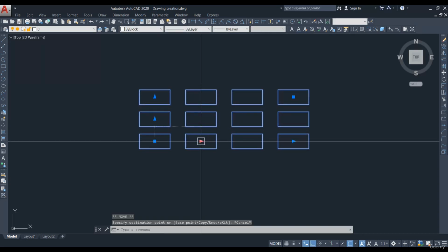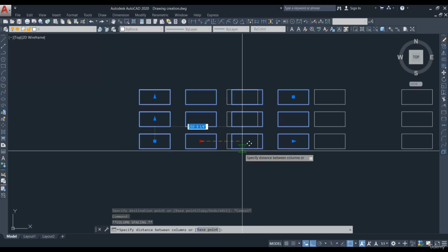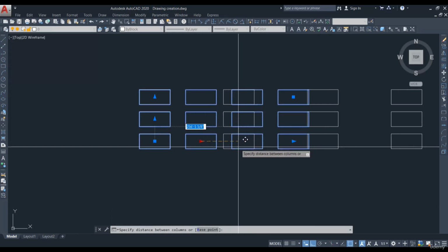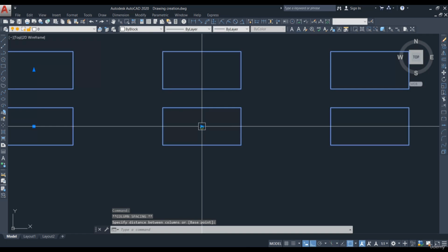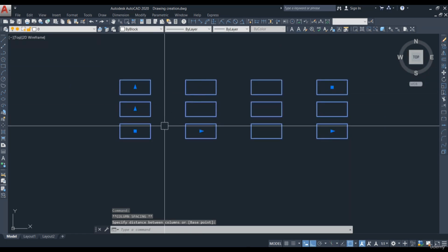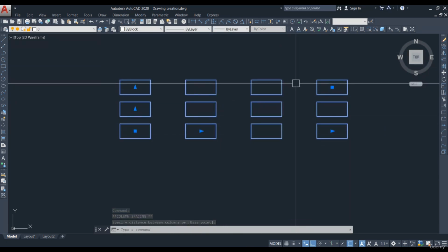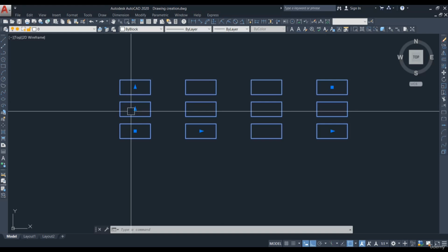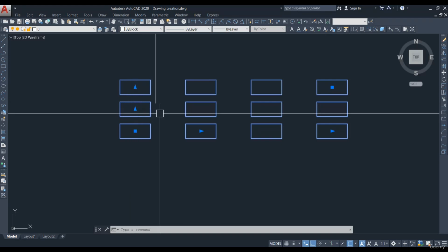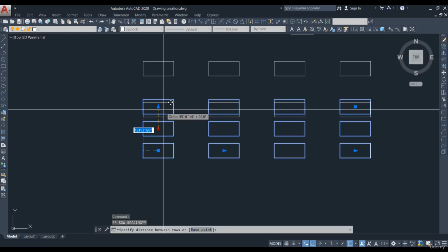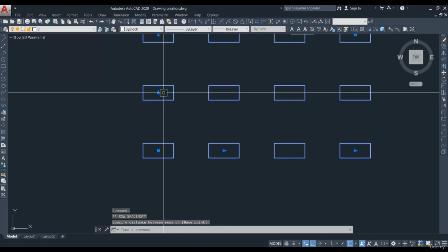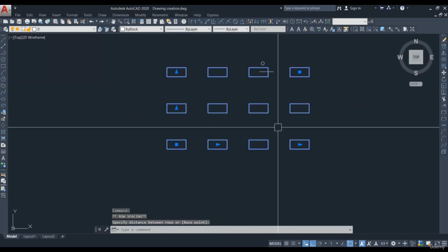And after that you have some blue arrow here. By clicking this, you can change the distance between the rectangle objects. I am just dragging like this and then clicking over here. See, you can see the distance between the objects in this direction. Similarly, this arrow mark will be used to increase the distance in the vertical direction. See, I am just dragging this and then clicking over here. The distance has been increased now.